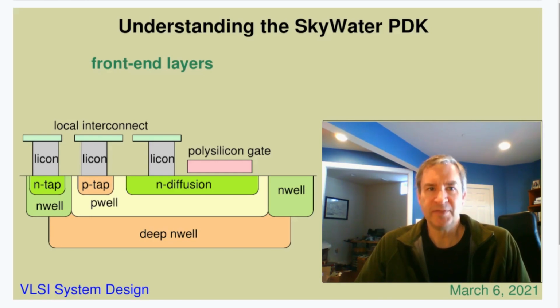This isolation comes at the expense of the area required for surrounding the whole deep n-well region with an n-well ring to completely isolate the P-well region on all sides, and a large required spacing between the separate deep n-wells if multiple isolated domains are needed. However, the improvement in noise isolation is worth those drawbacks.